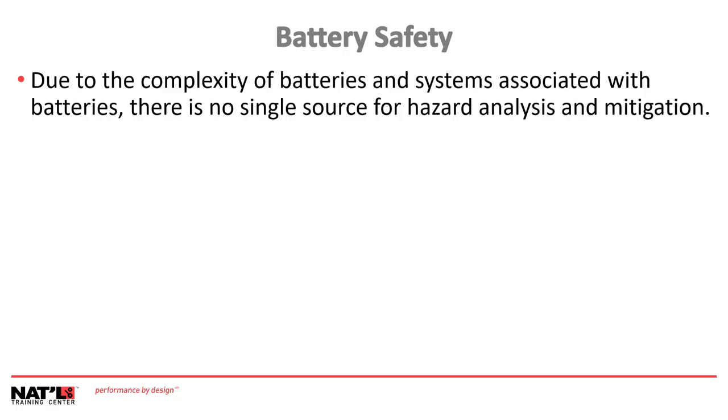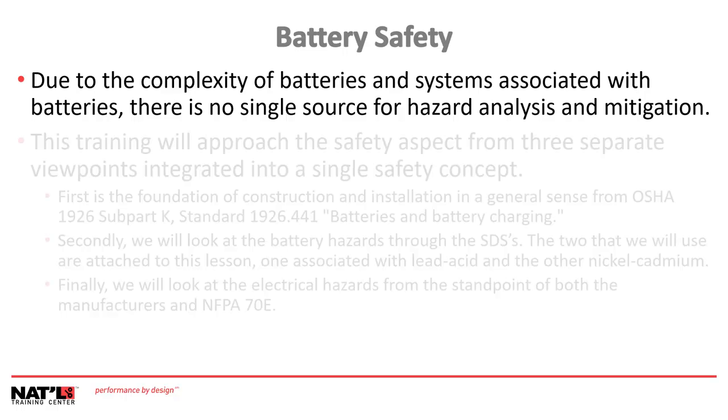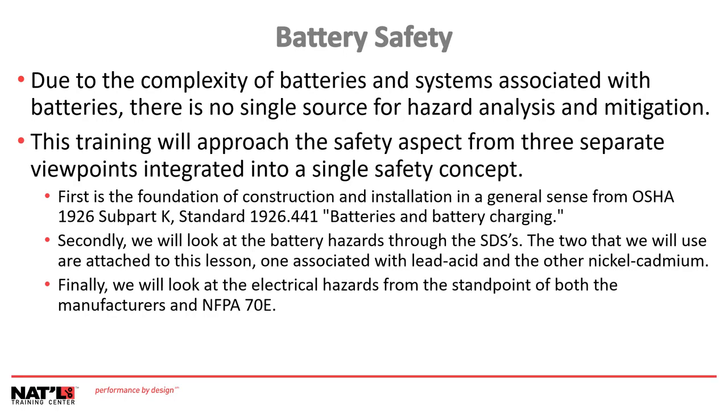Due to the complexity of batteries and systems associated with batteries, there is no single source for hazard analysis and mitigation. This training will approach the safety aspect from 3 separate viewpoints integrated into a single safety concept. First is the foundation of the construction and installation in a general sense from OSHA 1926 Subpart K, Standard 1926.441, batteries and battery charging.